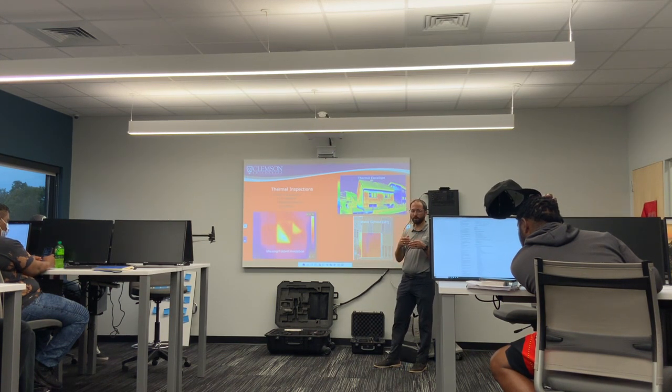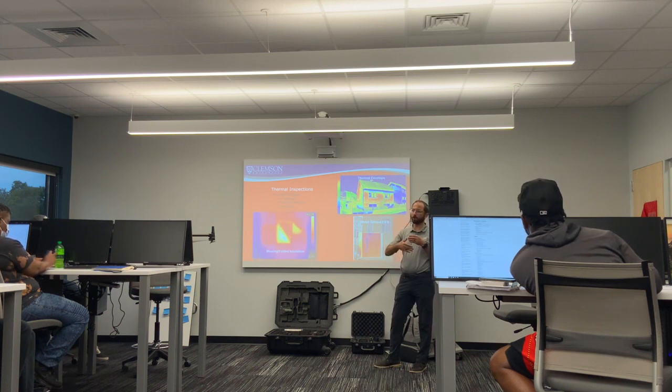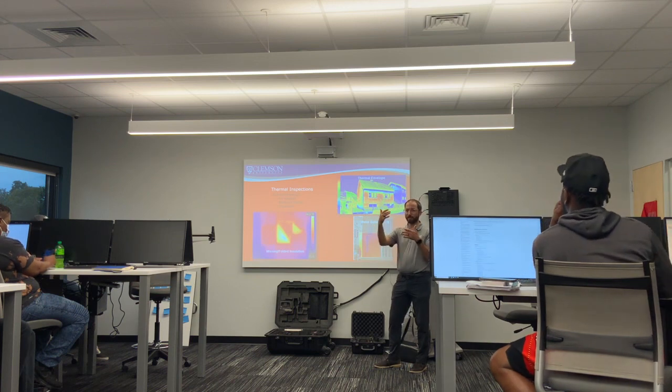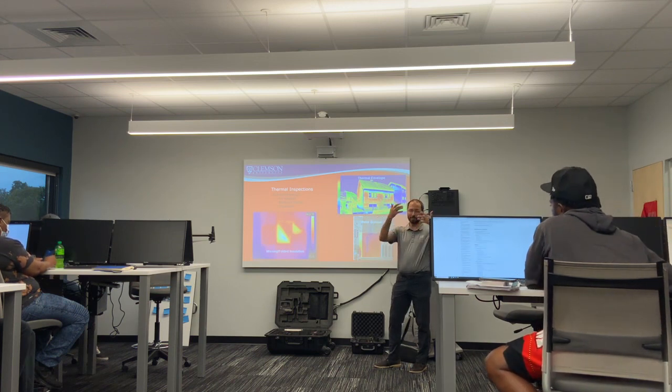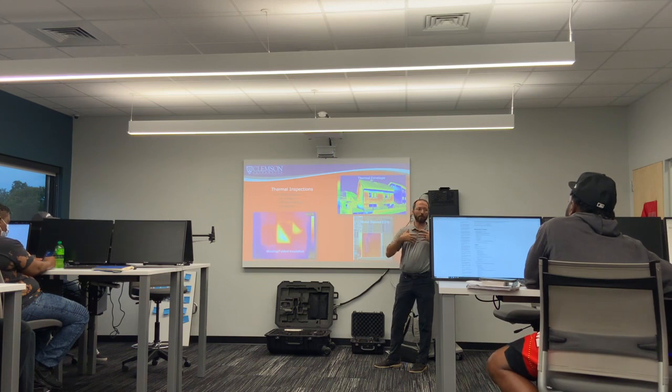most commercial buildings' window systems have some sort of gas in between two pieces of glass, and if something happens on the installation or throughout the life cycle of the building, and that seal gets broken, that gas ultimately leaks out. The gas is essentially in there to prevent thermal exchange, the sunlight coming in.